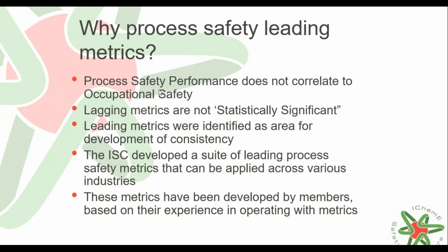A process safety event is basically when one of those barriers that you've got defined is called upon to act. That means that you're in a situation where one of those items that you're relying on for your safety performance has found something that needs to be fixed or rectified. And that can be either hardware or soft systems. But in the event that one of those items has been activated in anger, that will indicate that something's gone wrong.